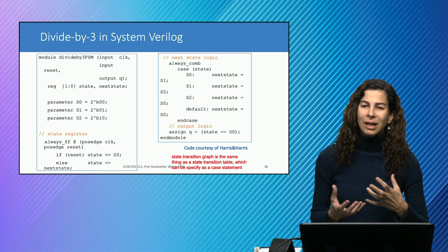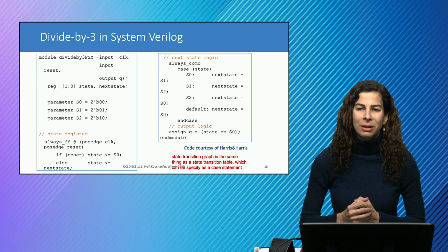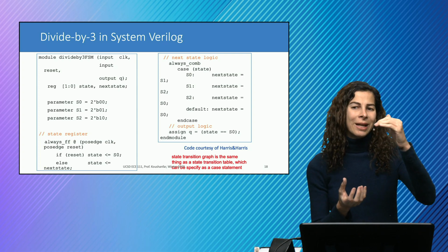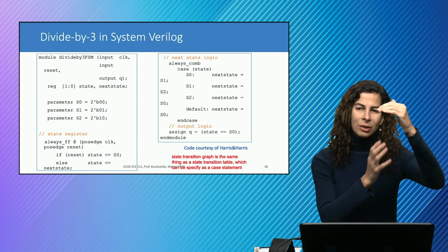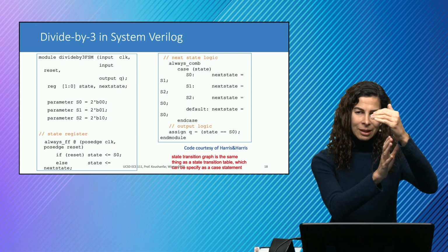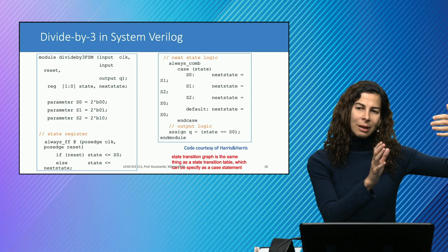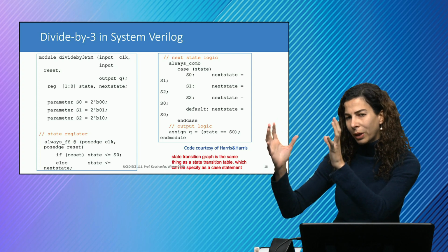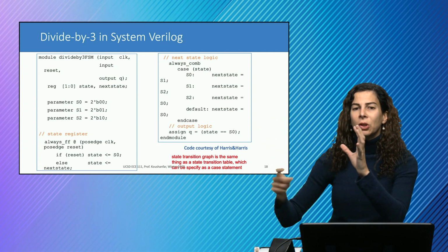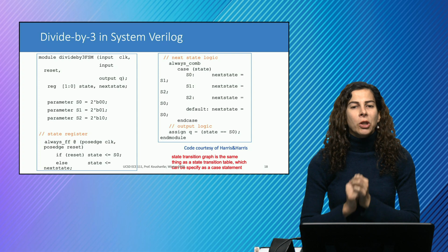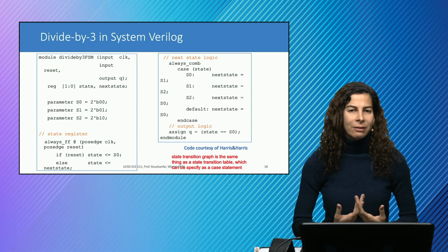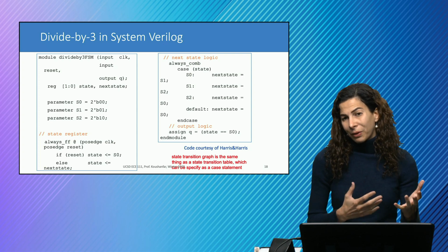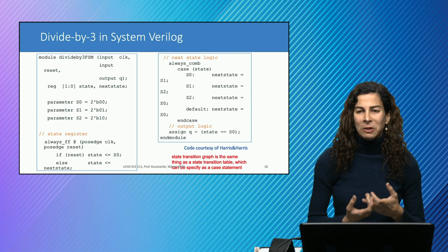And the template is kind of following what we had in terms of a Moore state machine. Remember, we had that block diagram which said your next state logic is going to come from the current state in the registers and the inputs applied, that gives an input function, and then the states are going to go through a combinational function to generate that output for us. So let's just divide it like we said. For the divide by 3, it's a very simple circuit.